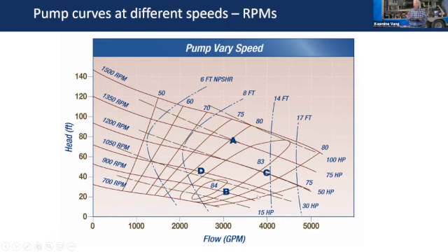But remember that people think, and I've had examples of this, where they put a VFD in, think it's going to magically save them energy. And they look at their bill and they don't see them saving any energy. If anything, it has gone up a little. And they've come to me and asked, why not? And I said, well, how are you running it? And they said, well, I run it full speed all the time. That VFD is going to save energy. I said, no, it doesn't. It only saves energy when you slow the pump down. Go to a different RPM, lower speeds.